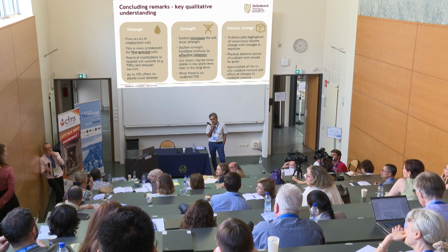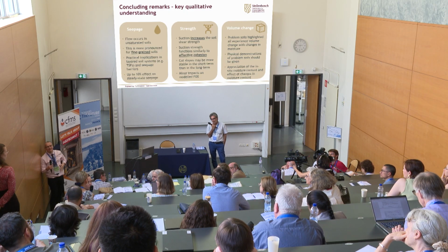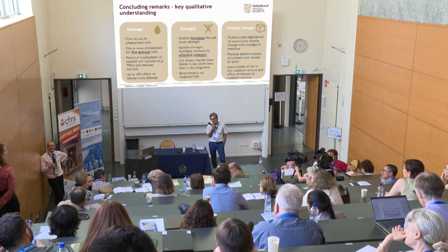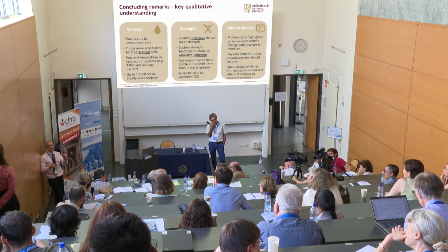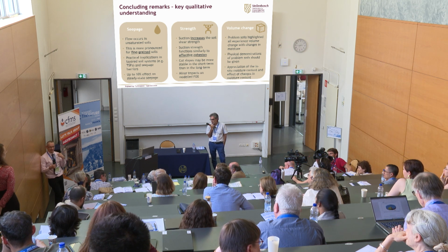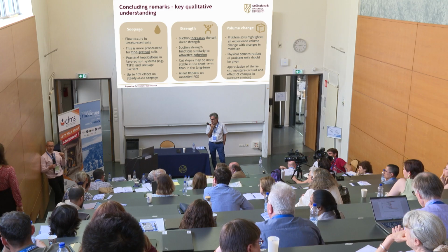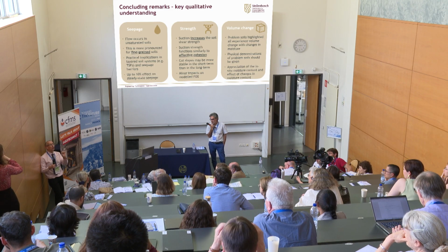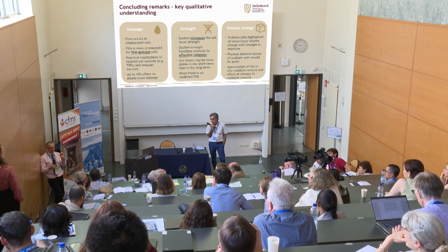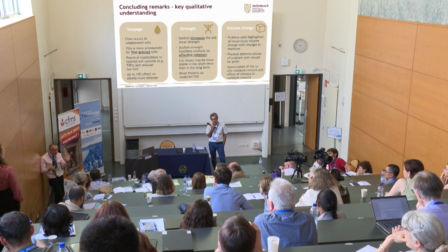I know what you're saying, and this happens to my students sometimes in other classes too. I ask them, why did you use the dry soil? Because we tell them that above water, the soil pressure is zero. Because we tell them that the soil is dry when calculating the effective stress. That's our mistake. We should tell them that to calculate the effective stress, we are making the assumption that the pore pressure is zero, which has nothing to do with the dry soil.